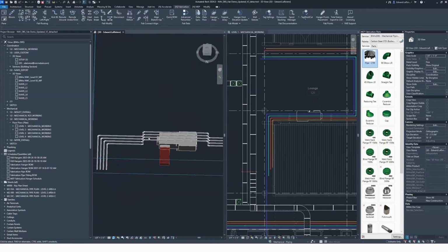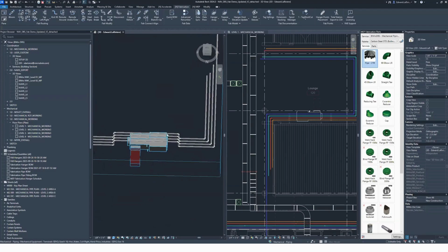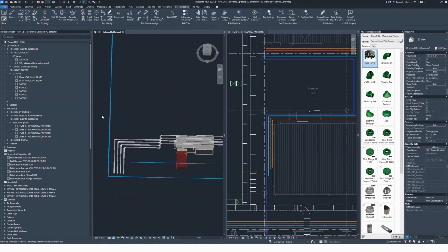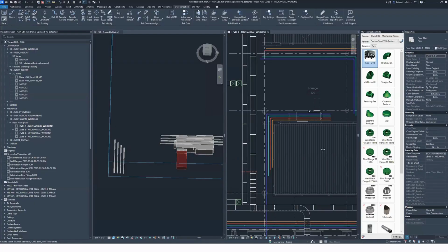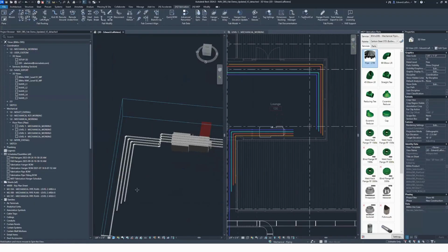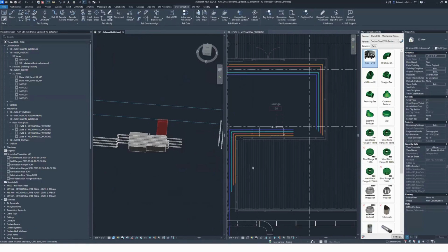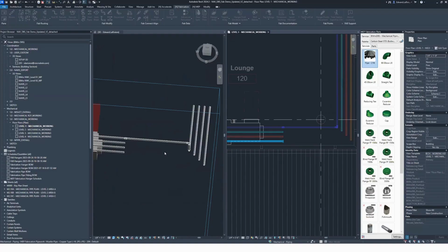Then maybe we want to start minimizing some of this because that's a lot of extra bends that maybe we don't need. Maybe you just use this to go get that top piece in here and we think about coordinating the rest after. If we jump over to the left, I can go ahead and delete some of that out. I guess that's the right if I reorient myself to match our page here. There we go. We might even find some of these things that Revit does do well, like trim. We might have some other options in here that we could do instead.